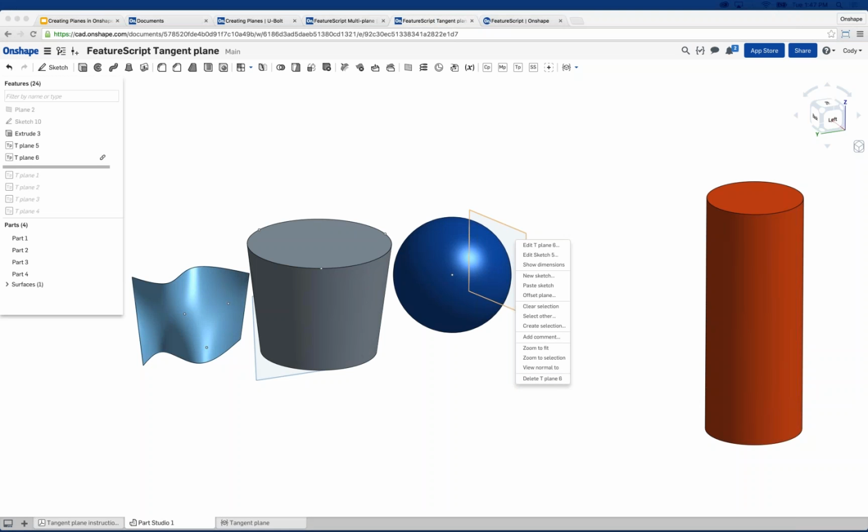All right, question. Will the plane distance automatically change when I change the line size? And the answer is yes. And that's one of the benefits of using a line as a reference. It will reflect your intent. If you change the line, the planes will automatically space out to accommodate for that change in distance.